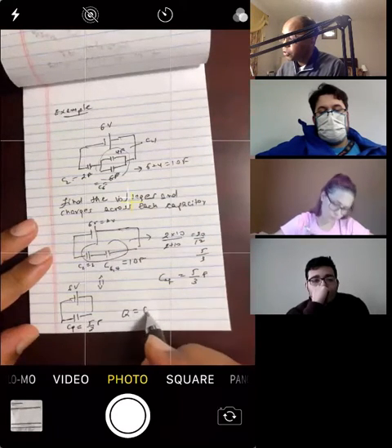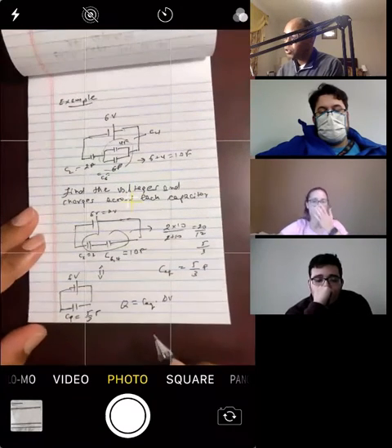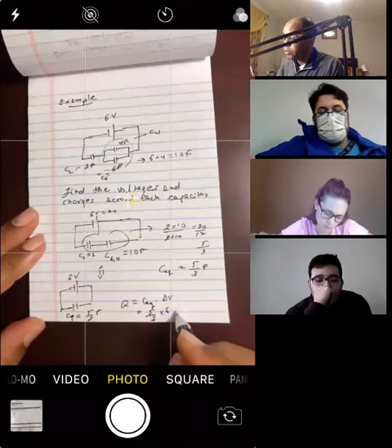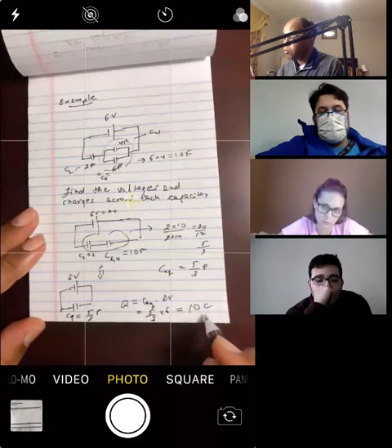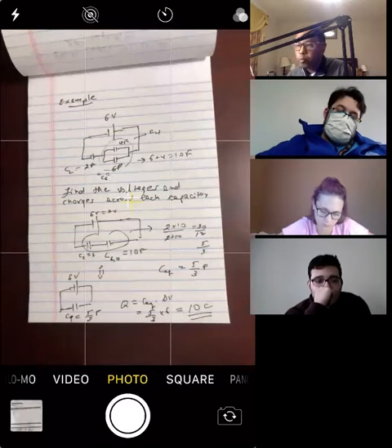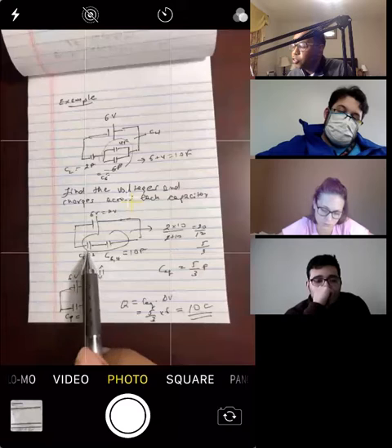So the total charge is CEQ times delta V, which is 5 over 3 times 6, that's 10 coulomb. Okay, so the total charge is 10 coulomb. But remember, this is a series combination of these two. So what do you think are the charges in here?